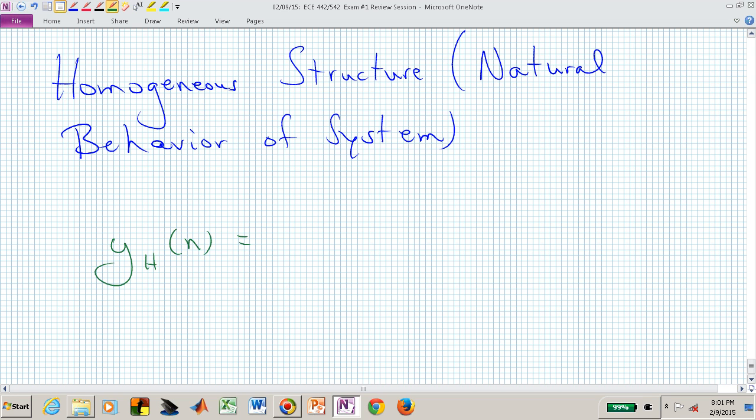You had two poles, didn't you? You have two modes. We'll talk maybe a little bit later if you had complex poles. If you had complex poles, you would have their radial distance and their angle that would influence their structure. Here, we had real poles. We had one pole at 0.5, so we could say, scale that by an alpha 1, and that's 0.5 to the n. We had another pole at 0.9.